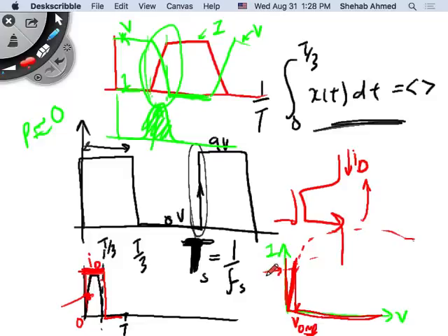This equivalent resistance, if you look at the MOSFET's voltage and current curves, is a linear relationship in this portion here. If we're operating in the triode region, in this part of the curve of the MOSFET, then there's a linear relationship between current and voltage across the device. So in 325, we took the inverse of the slope of that and called it a resistance, the channel resistance.